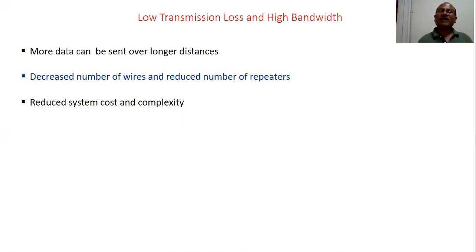So a repeater is a kind of amplifier, or a combination of amplifiers, maybe a cascade of amplifiers, intended to strengthen, to boost, to increase the signal strength. So why? The signal strength becomes very high, therefore the transmission loss is less. And for equal transmission loss or equal distance, the number of repeaters required in optical communication, as compared to a conventional communication system, will be much lower.